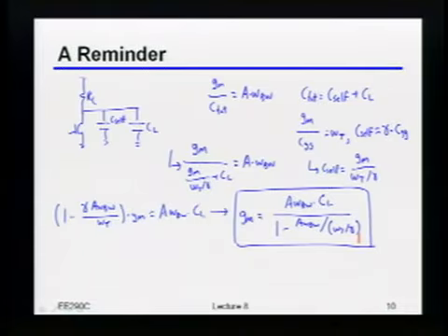By the way, maybe just as a reminder, how much power do you have to spend if you had a perfect device? And by perfect, I mean infinite omega t. What's the GM you need to spend to drive a certain load cap with a certain gain bandwidth? Great expression, right? Which is what?